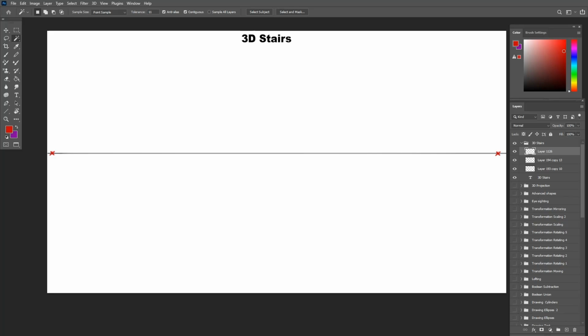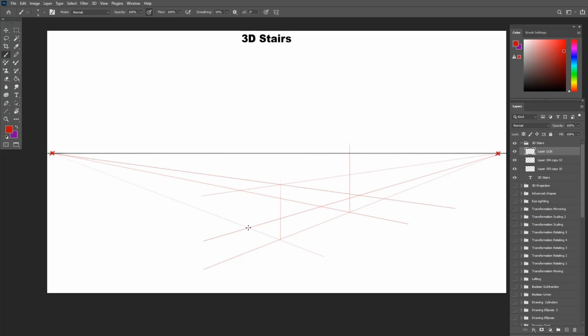We can do it with everything we learned so far, but with a bit more information. There are a couple of ways to draw a staircase. Let's start with one of them. First, I draw the top plan of the staircase, where the whole stairs will fit in. Then I choose how high I want the stairs to be, basically drawing the bounding box for the whole staircase.